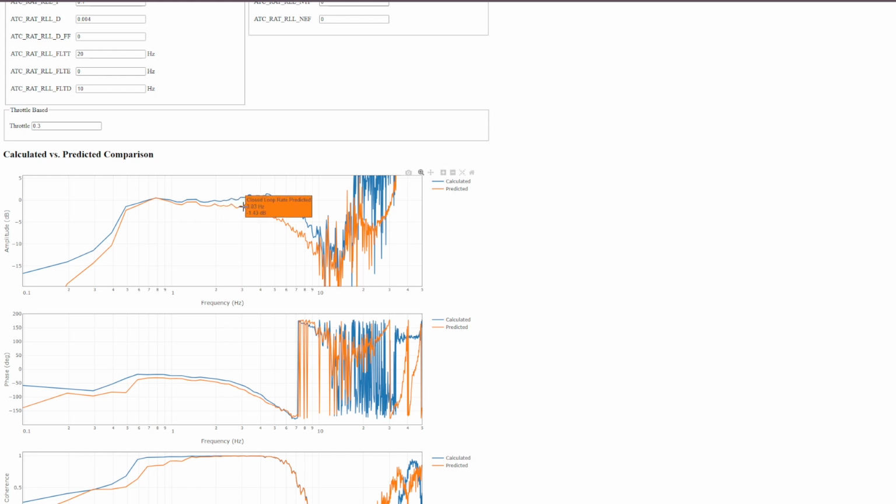As we go to higher and higher frequencies, the output gets smaller and smaller, but also it falls further and further behind the command. So this is basically like putting a sinusoidal input into your sticks and going faster and faster. And one of the key points you want to look at here is 6 dB, where the output is half the size of the command.